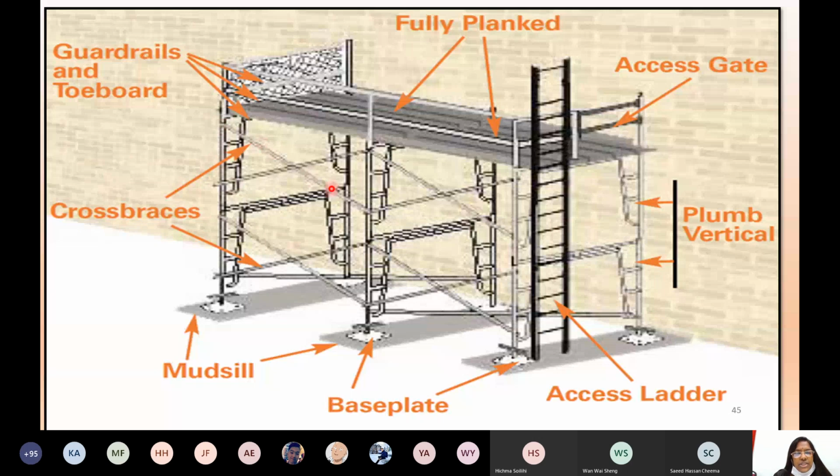And then these are the cross bracings. This is what we said just now. The bracings have to be evenly spaced. You cannot have only one cross bracing for a whole length, not like that. There are chances of bending. So it should be properly designed such that the number of bracings depends on the height or on the length it is running. These cross bracings and the horizontal bracing should be properly planned, and the number should be maintained for successful formwork.